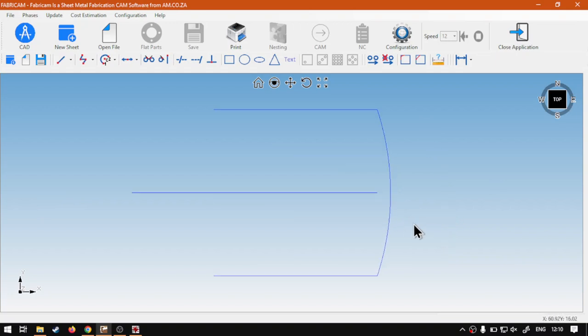Then another thing to keep in mind, that you might think, okay, I'm going to use this as my point, rotate it around it, so I've got a nice circle. Select the tool, we select 1, 2, 3, and then you notice nothing happens. So if these lines are all parallel, unfortunately it does not work as an actual point, so just make sure you offset it a bit if you want to get a better result.